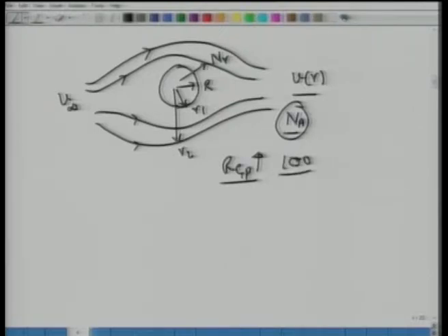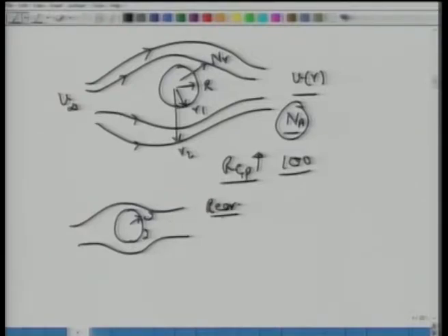If it's very large, say 100, then there is uncertainty in the velocity profile. And if you recall from aerodynamics, we will have cases of boundary layer separation, etc., or the eddies which are formed at the rear end, in which case it's hard to predict the diffusion flux in terms of your bulk transport and diffusion flux, and it involves a lot of error here. In these cases, it's possible to define a mass transfer coefficient quantity